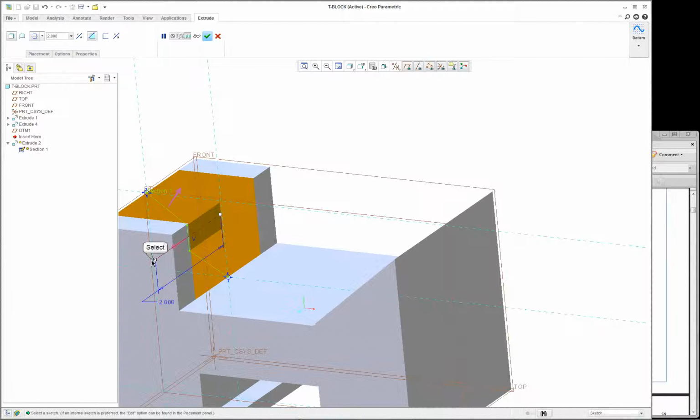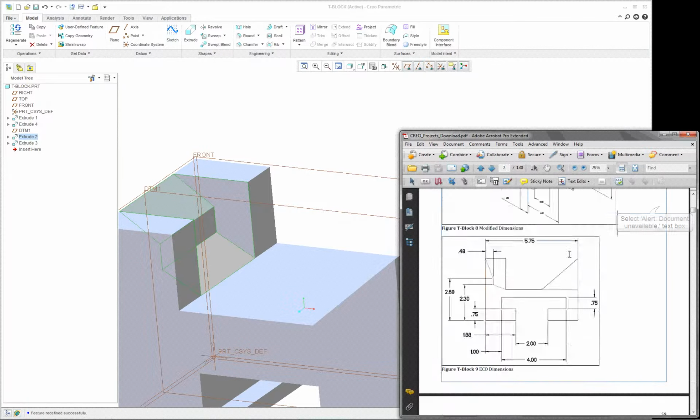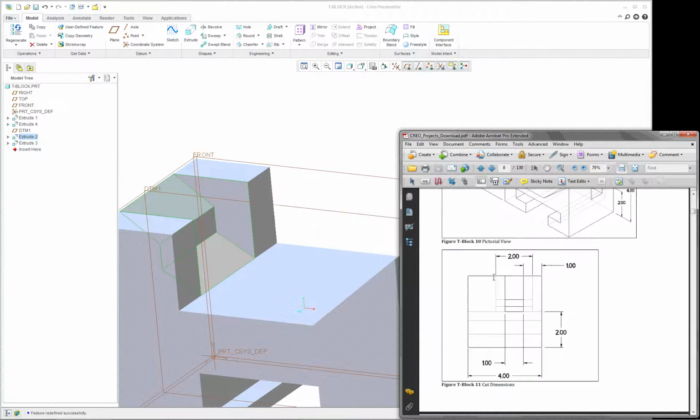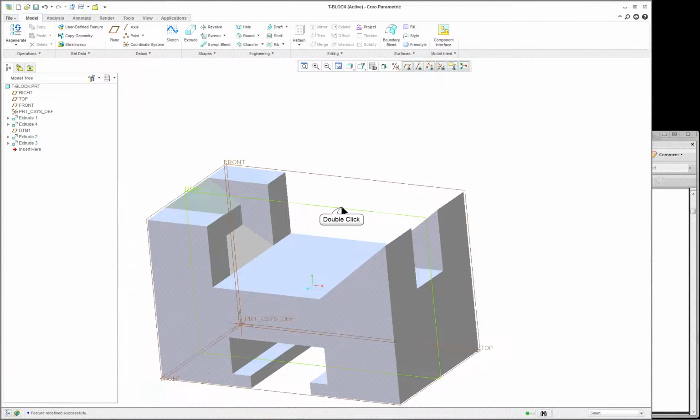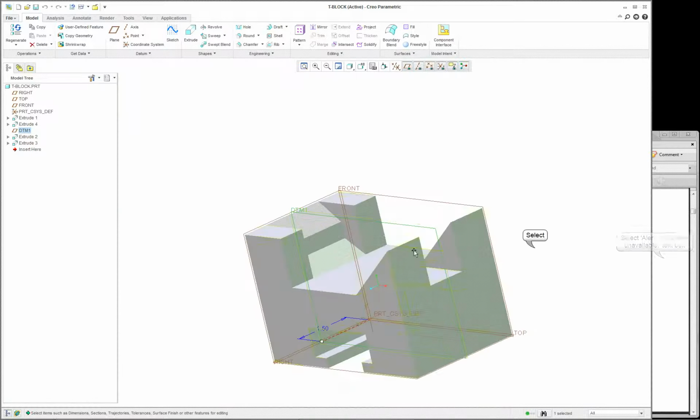There's the direction it's going to be removing material. And we'll finish it. Now, one of the problems is we didn't bother to look at the view that's from the end, and we're going to notice that it's not down the middle anymore. It's actually 1.5 inches in. So in other words, when we offset this datum plane 1.5, all right, that's correct.